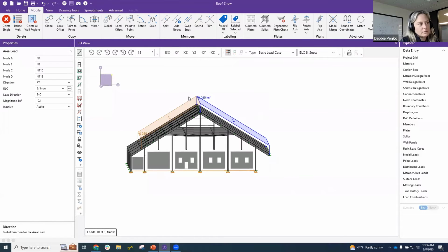The idea being that, if you're in snow country, you already know all this, I'm sure, but as snow falls, it's on a straight horizontal view. The snow is coming down. So whether you have a high slope or not, it changes how much horizontal area you're actually going to see, how much square footage is going to get that load. So it's a projection. So 100 pounds is not really 100. It ends up more on a projection. You can adjust it manually, but if you do it this way, it'll also project it for you.